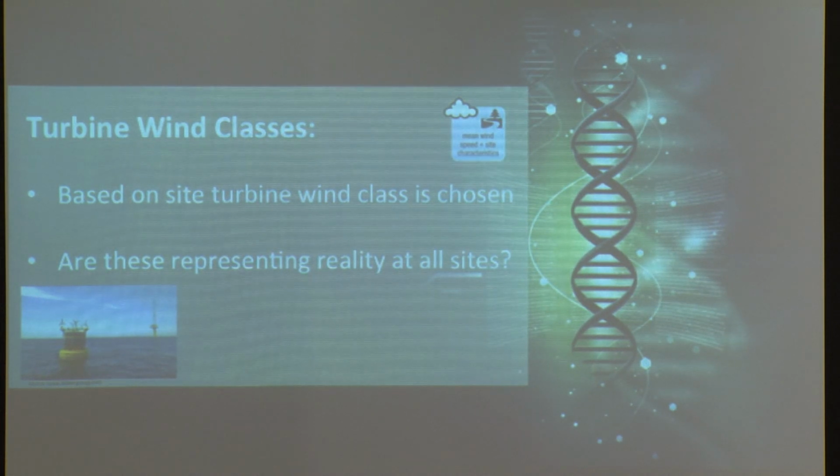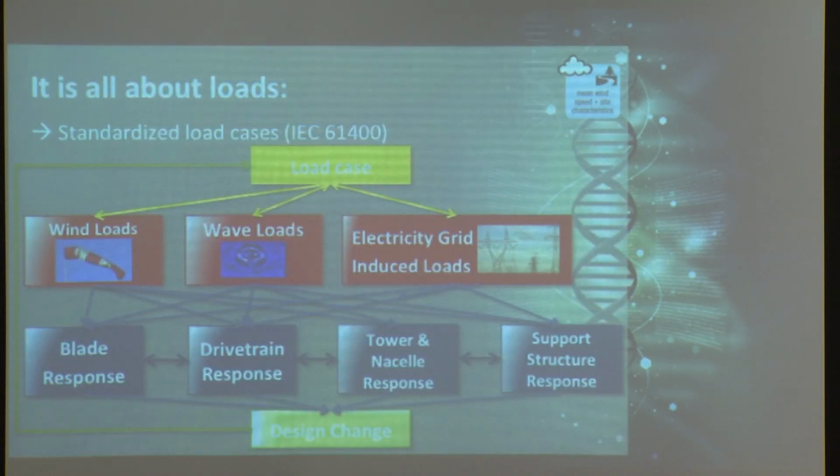It actually all starts with loads. In the beginning of your project, as I discussed, you assess the loads, and the loads are actually the starting point of everything. In the standard, you have the definition of different load cases. They comprise wind load, wave load, and electricity-induced load. I will show an example there later.